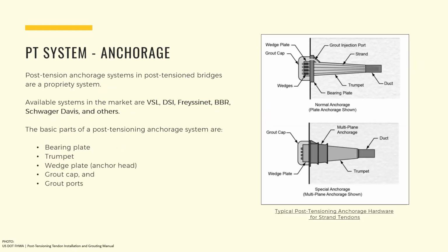Next, the post-tensioning anchorage system, which collectively refers to the technologies used in anchoring tendons, is a proprietary system. The basic parts of a post-tensioning anchorage system are the bearing plate, the trumpet, the wedge plate, which is also known as the anchor head, grout caps, and grout ports.